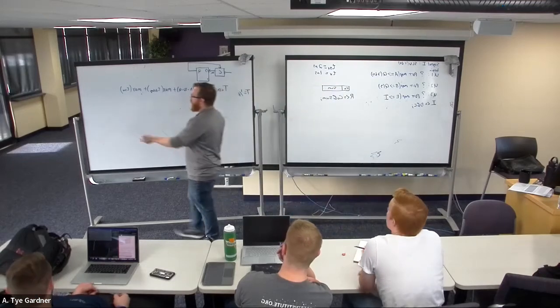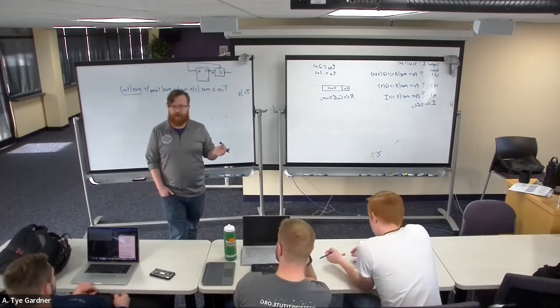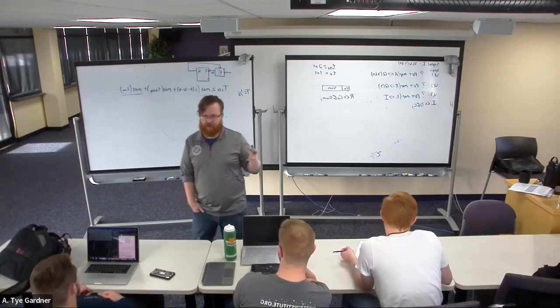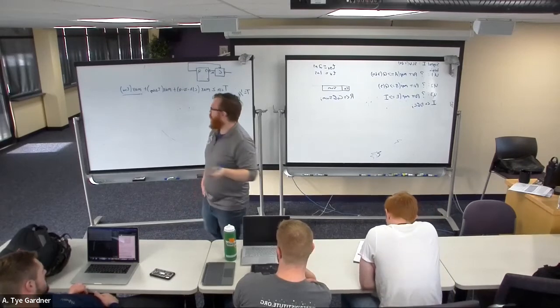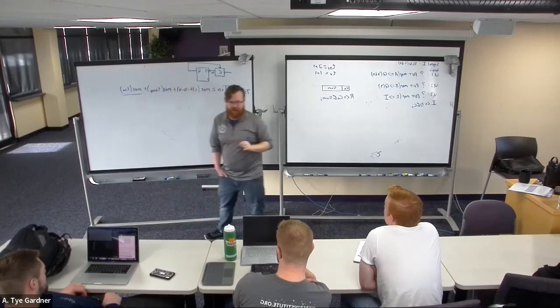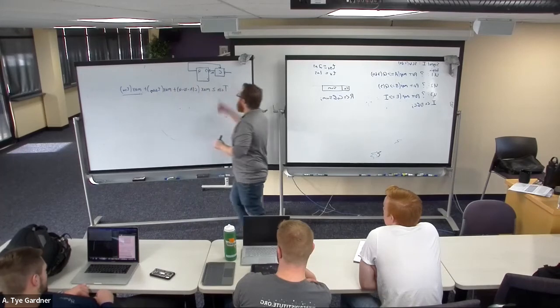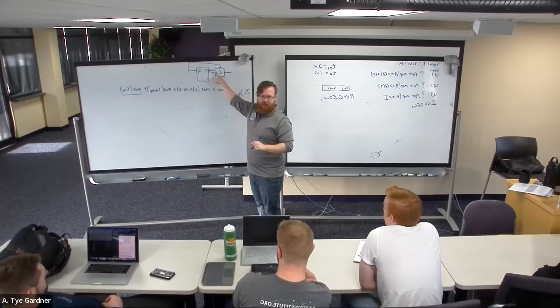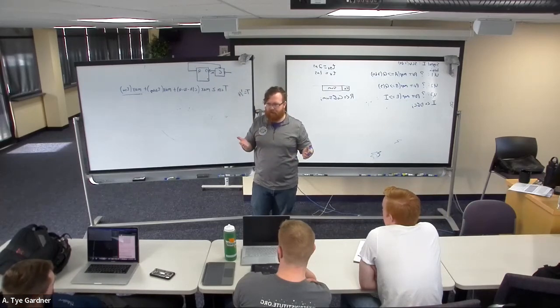Now this term we've already talked about, max setup time, which is what is your worst case setup time? Because when you get a data sheet, it's going to tell you like minimum, maximum. You want to account for maximum. What is the worst case situation? So the amount of time maximum expected for your device to set it up, plus the maximum time that you would expect the delay through the combinational logic. Okay, we've talked about both of those. It makes sense that those would be part of the speed limit of your circuit.